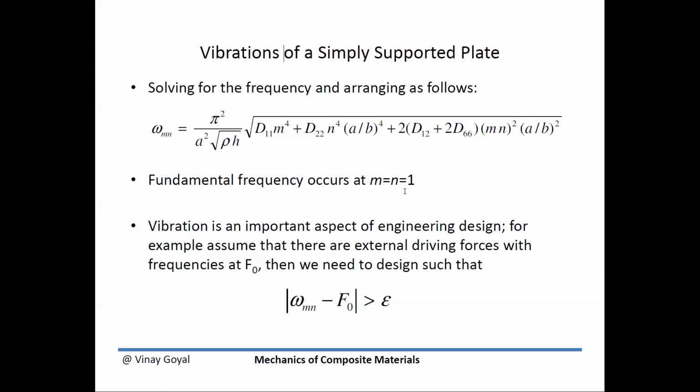And so typically in design, we want to maintain a separation between the natural frequency of the system and the frequencies of the driving forces, so they don't couple and cause a plate to fail. That is one of the things you can tailor composites for: you can drive the design to do so.